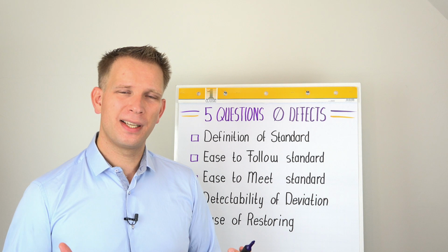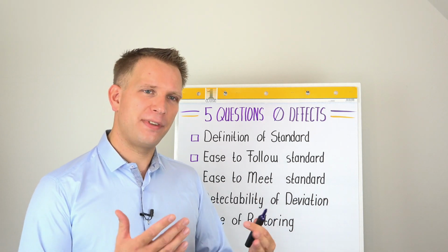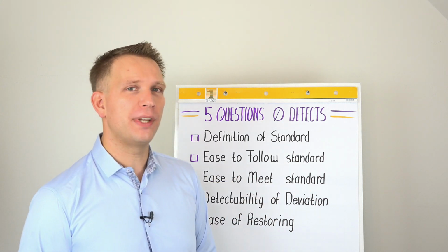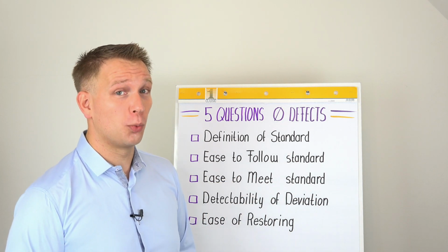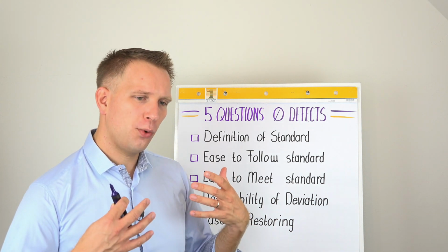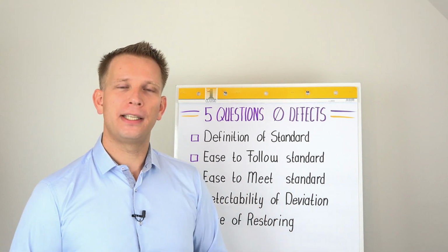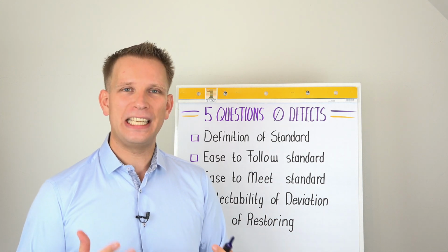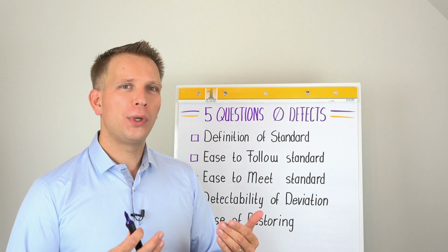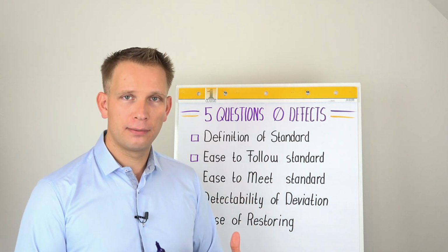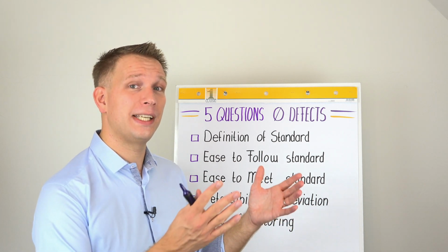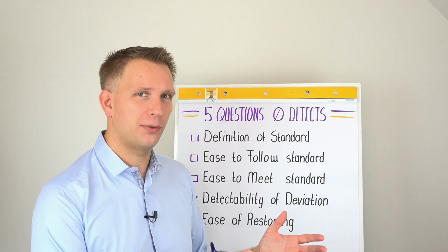Now the fourth question is about, if there is a deviation, how difficult is it to spot it? So hopefully there are no deviations, but in practice we will still be checking. And here we try to estimate how quickly you will find the deviation. So when a setting deviates, can we see it? And a level 1 would be only if you are really looking for it, or you cannot really see the setting deviate, you only see it with the product really going out of bounds.